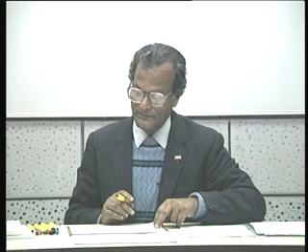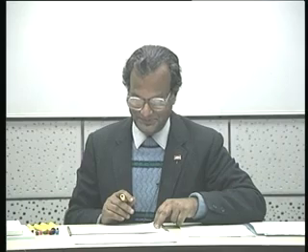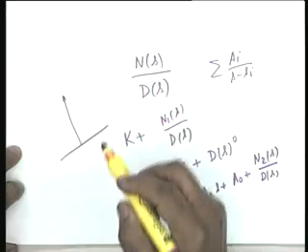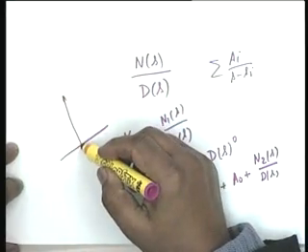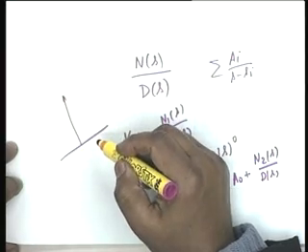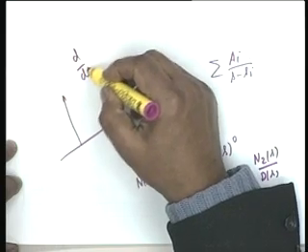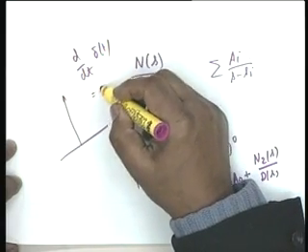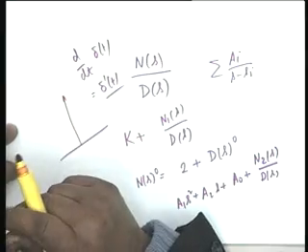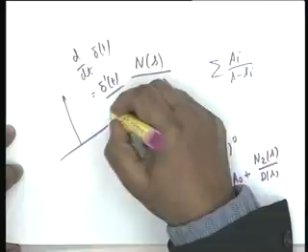Okay. So what is the representation of differential of delta t in the time domain? In the time domain, well, it's doubly infinitely large. You are differentiating a discontinuous function which is 0 at t equal to 0 minus, 0 at t equal to 0 plus, it exists at t equal to 0, the amplitude is infinity. So you are differentiating an infinite function and it is only a conceptual quantity, however its Laplace transform exists. Laplace transform is simply equal to s.